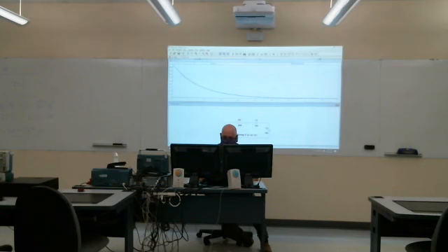So I don't know why LT-SPICE does that, because it does lead to problems here. If you leave the rise and fall times as 0, it actually defaults to, I want to say a millisecond or something. It's kind of a long rise and fall time. You just have to put in something that's non-zero there to get what you want. And so